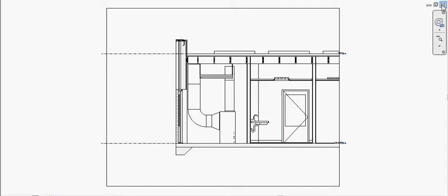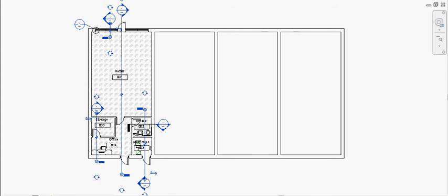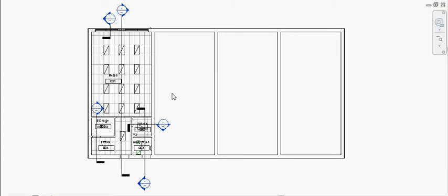And then to the ceiling plan, which shows the same section cuts. And here I have my light fixtures, pretty spaced out to kind of how I want them to look. The bathroom and the HVAC room have a fixture. The office has one fixture, and I know I'm going to have to place additional fixtures in that room there. One light fixture will not be enough.